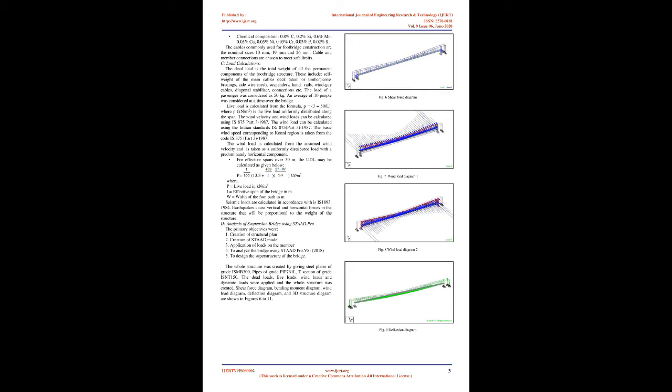The terrain profile at the proposed site is flat with minimal variations in the ground levels. The longitudinal gradient of the structure was restricted to 5%. Cables are the fundamental elements in cable-supported structures. For that reason, choosing among the different existing types requires special consideration. The general characteristics of the steel used.